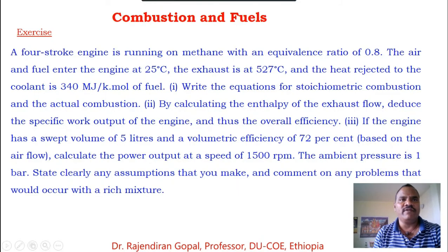Welcome you all. Today we are going to discuss one more problem in fuels and combustion. It says that a four-stroke engine is running on methane with an equivalence ratio of 0.8. The air and fuel enter the engine at 25 degrees centigrade. The exhaust is at 527 degrees centigrade. And the heat rejected to the coolant is 340 megajoule per kilomole of fuel.